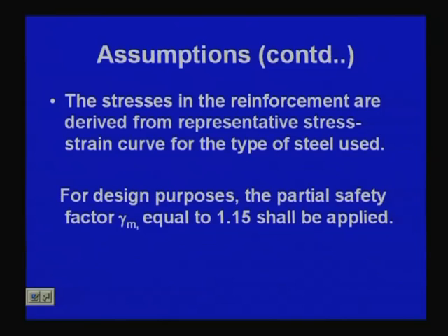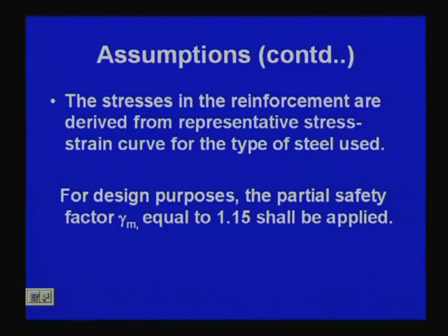So, if fy is the yield stress, we have to consider fy by 1.15. We never take the ultimate limit for our design calculation.